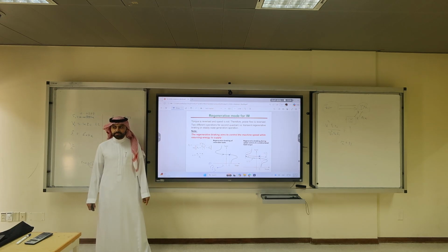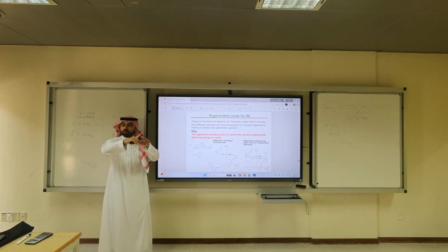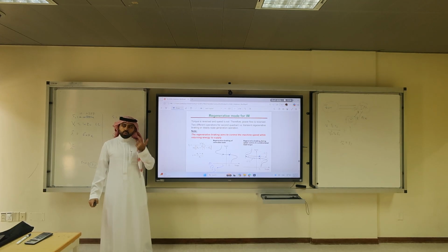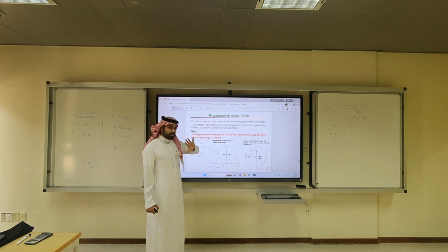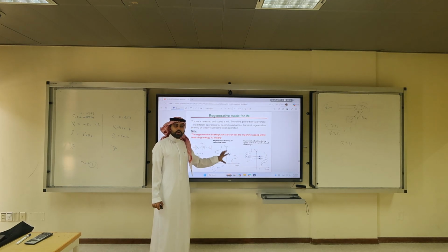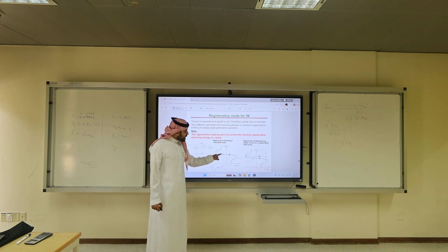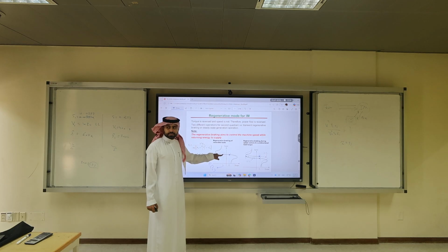Think with me. In the car, when it goes up and then comes down, when it goes down suddenly the torque becomes negative. What is my operating point here? It is the cross section between the load torque and the capability torque. I'm not drawing the motor torque here, it's complicated. But I know that at point 2 is applicable because I'm going to experience negative torque. So I can run my machine on this curve.